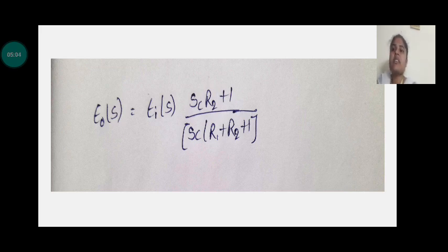The compensator basically introduces a pole and/or zero in the open loop transfer function to modify the performance of the system. The compensation schemes used for feedback control systems are either series compensation or parallel compensation.